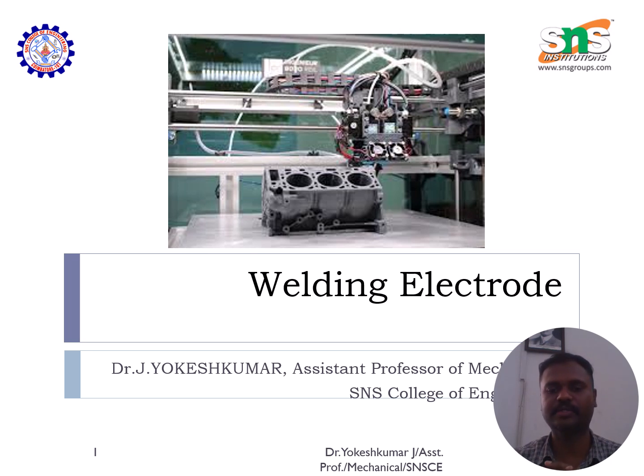In the arc welding process, one of the important components used is an electrode. The electrode is the main medium which converts electric current into an arc, and the arc is struck between the electrode and workpiece, which is used to heat the raw material or the parent metal to its molten state. Then finally, it is melted and joined together. So it comes under the fusion welding process.